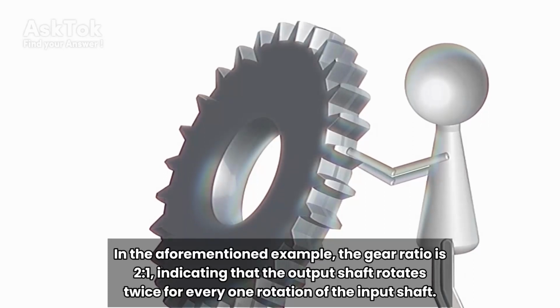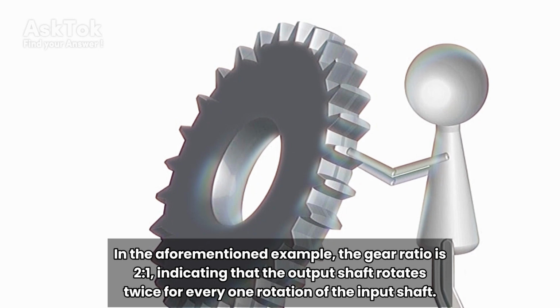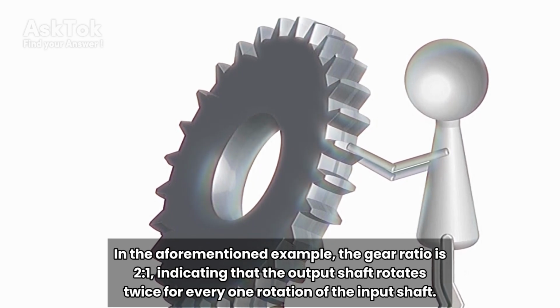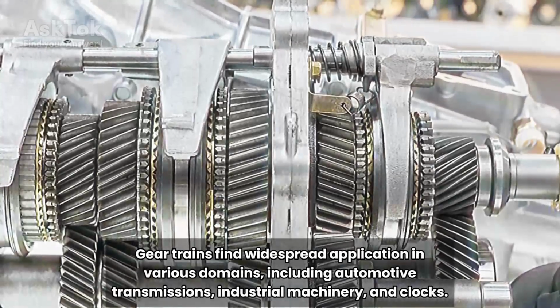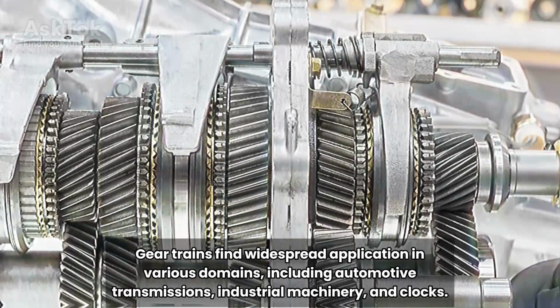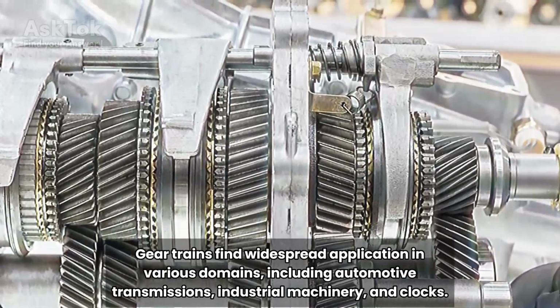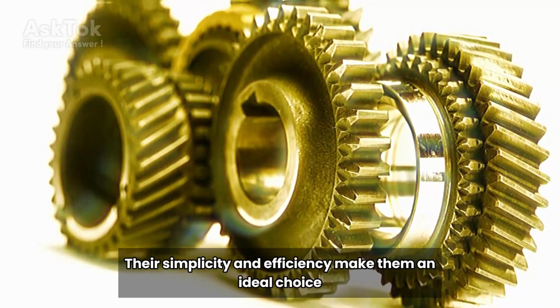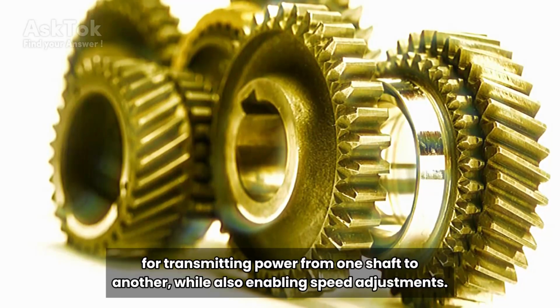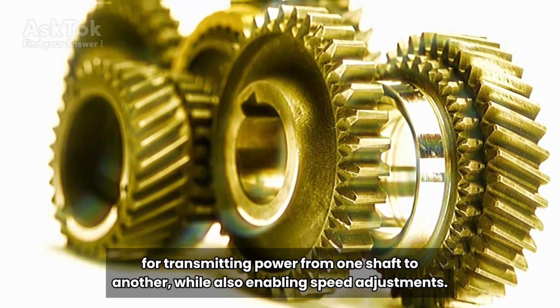In the aforementioned example, the gear ratio is 2:1, indicating that the output shaft rotates twice for every one rotation of the input shaft. Gear trains find widespread application in various domains, including automotive transmissions, industrial machinery, and clocks. Their simplicity and efficiency make them an ideal choice for transmitting power from one shaft to another, while also enabling speed adjustments.